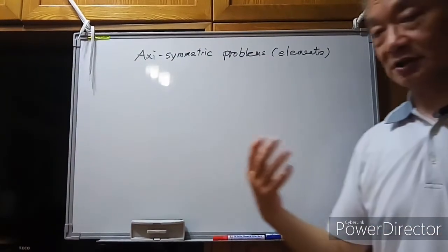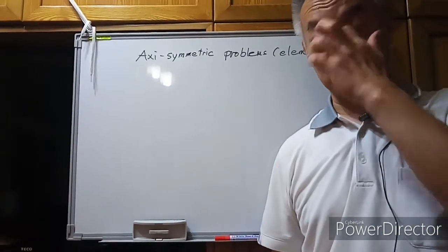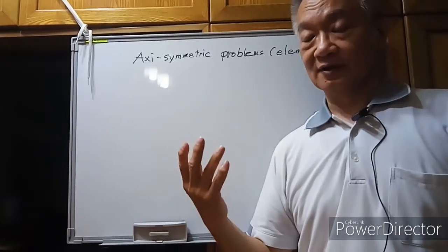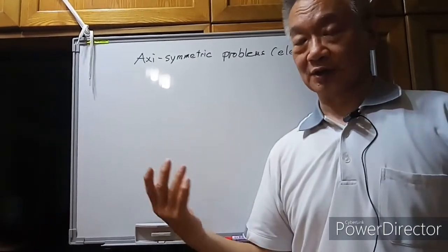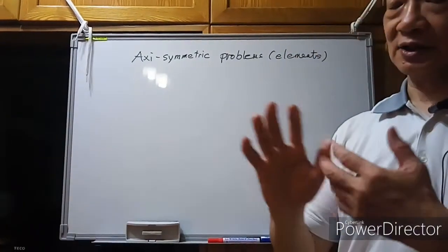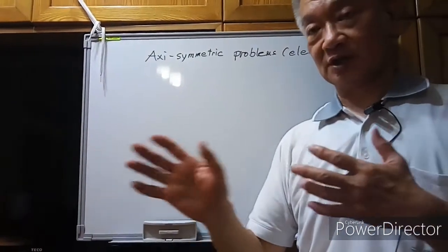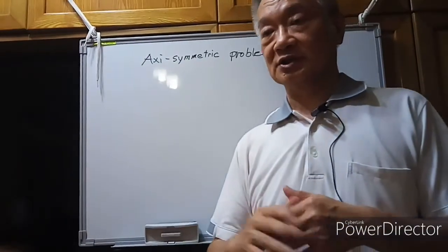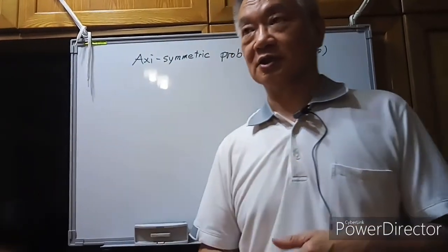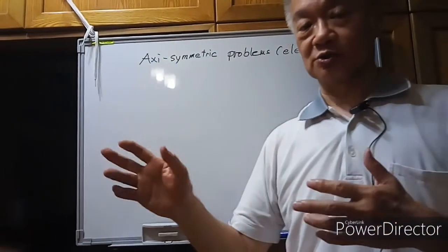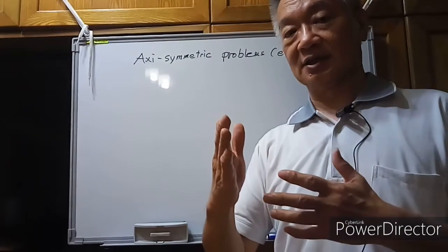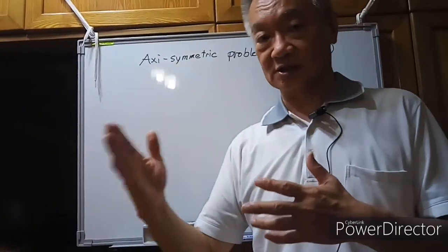It is similar to the plane strain problems. The displacement has some special character. Since we have assumed, for example, for the plane strain problems, that the dimension along the z direction is close to infinity, we cannot expect any displacement along the z direction.